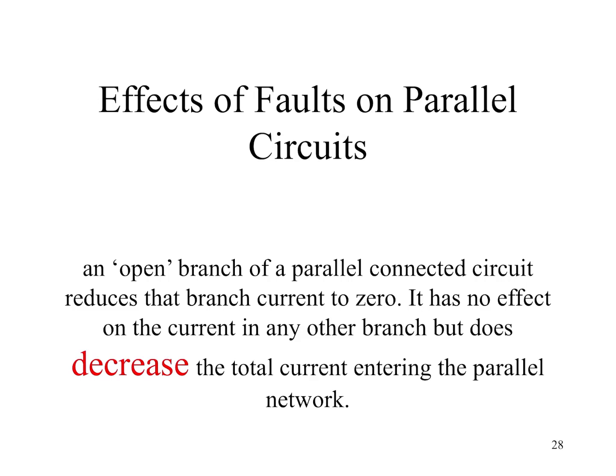So by principle, we don't look at the effects of a short in a parallel circuit, with the understanding that in a practical circuit, like a short on one of your receptacles in your home, what happens? The breaker trips, you have to remove the short before you can restore the circuit and enable the breaker again. So we're looking only at opens when it comes to a parallel circuit.